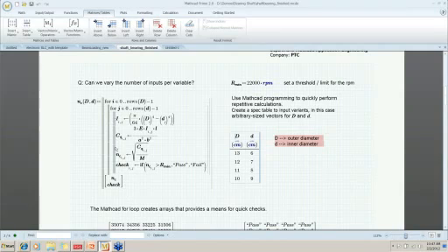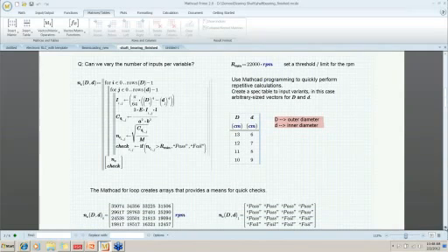And in this Mathcad inline program, we have 2 for loops that are basically looping over all of the outer diameters, all of the inner diameters, and performing this calculation, and then checking it to see if it satisfies a requirement for the minimum shaft speed. So here's a very straightforward if statement that says if our shaft speed is greater than the minimum, then we pass, otherwise we fail. We're going to return the shaft speed for all of these combinations for outer and inner diameter. So we'll have 16 results and 16 pass-fail results.